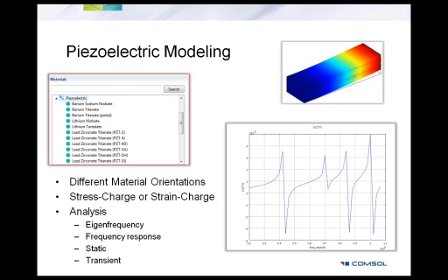And even with piezo modeling, the MEMS module lets you perform stationary analysis. You can do transient analysis. You can do modal or eigenfrequency analysis to calculate the resonant frequency. You can also do frequency response analysis. So yes, even here you can calculate admittances, impedances, all your parameters as well.